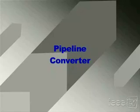That's a flash A to D converter. It finds the voltage and digitizes it immediately in one cycle. For very high-speed applications, that's the way to go. But it needs 100 rulers. It needs 100 measurements simultaneously. And the efforts of 99 people will be wasted. They'll not produce a useful result. So it's wasteful in hardware.